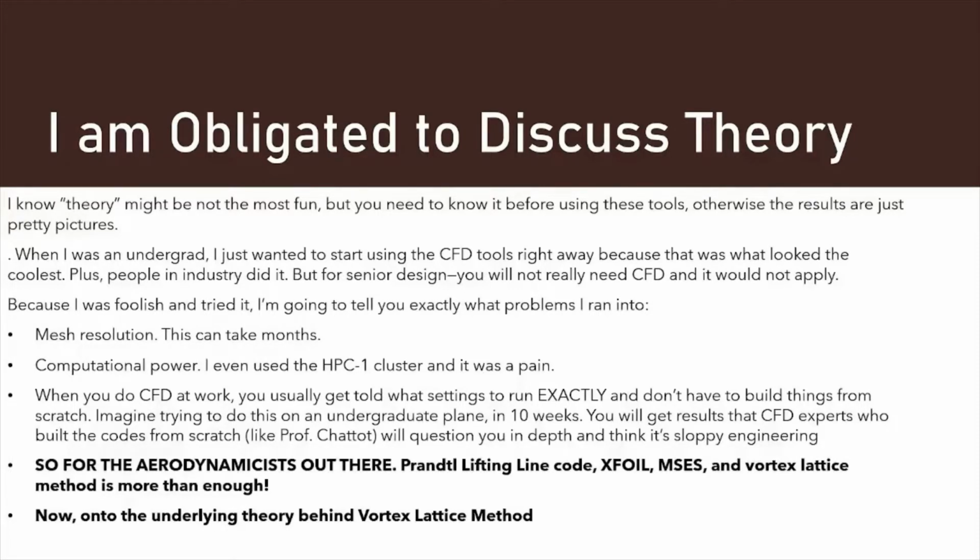Now, as you saw, I mentioned something called panel method. I'm sure you're kind of familiar with panel method from Professor Robinson's class. Basically, it gets the CP distribution on this 3D geometry, and from that you can back calculate the lift and drag. I do not recommend using panel method because I work on the VSPAERO software, and there's still a lot of stuff that's not great with it. Like, when you get your CP distributions, you'll start seeing a wild range of CP, and you're like, how did this happen? Well, it's because right now panel method is not the best way.